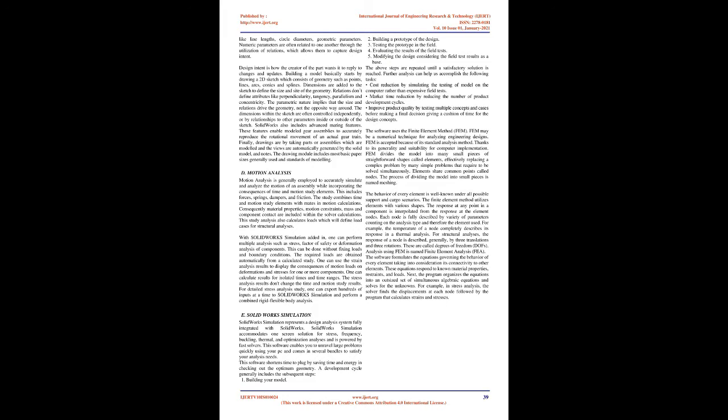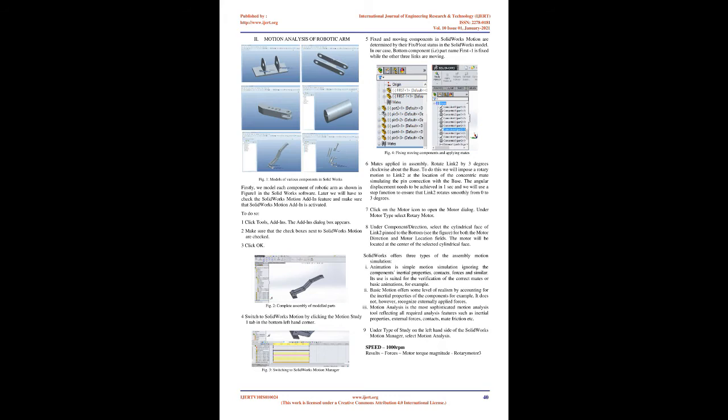4. The Provoc robot arm is defined as a 5-degree of freedom robot having all the joints as revolute. The kinematics problem is defined as the transformation from the Cartesian space to the joint space and the other way around. In this study the Denavit-Hartenberg (DH) model is employed to model robot links and joints. Provoc robot arm is a simple and safe robotic system designed for laboratory training and research applications.